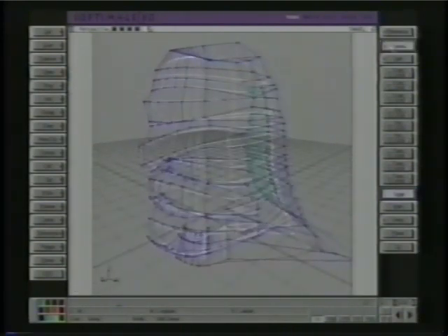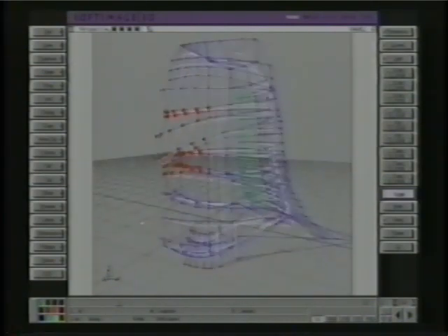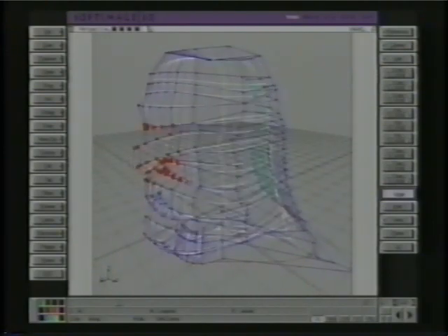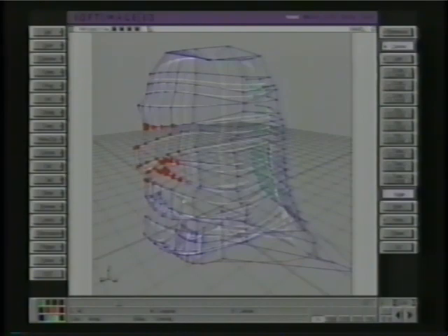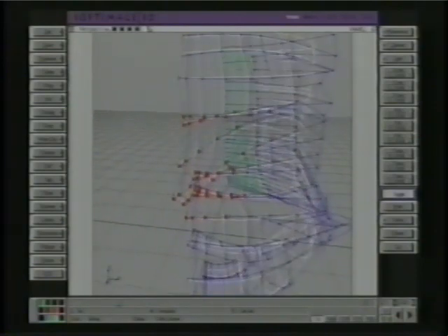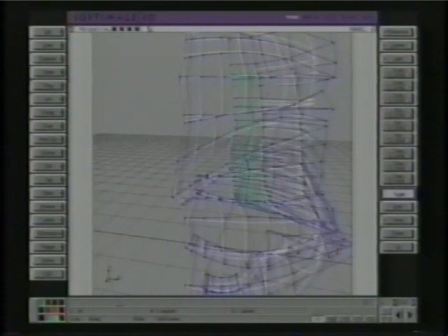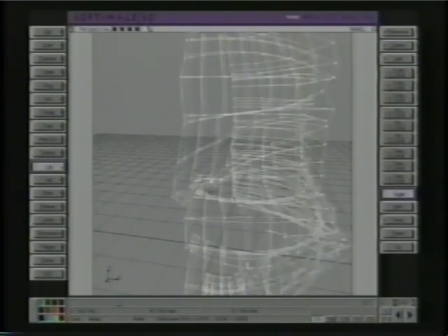You can use a feature called Frame Tag. What you do is you frame the area you want to work on, and then to zoom into that portion, do Camera, Frame Tag. Now we're looking right at that, and the interest of the camera is right in the proper place. I'm going to untag that and begin using Move Point again.